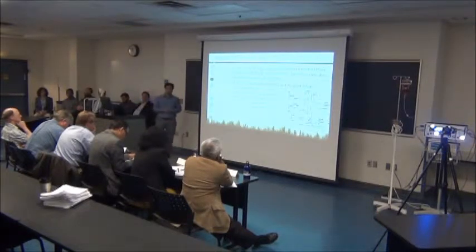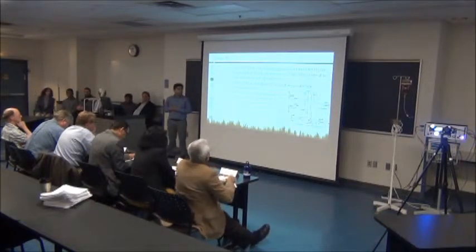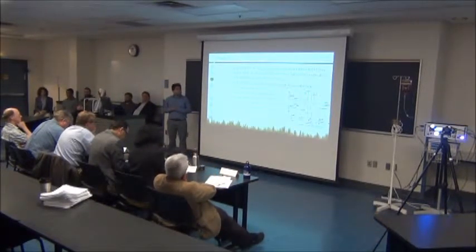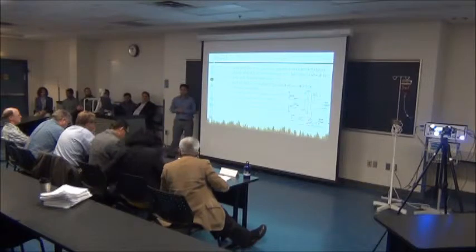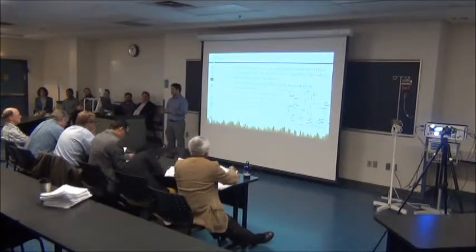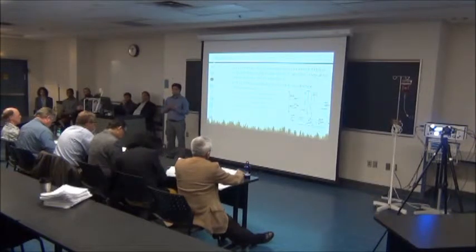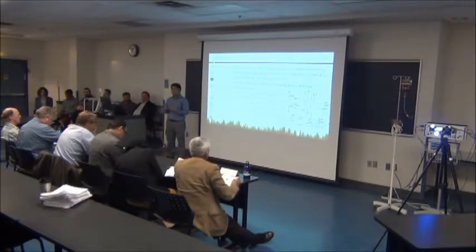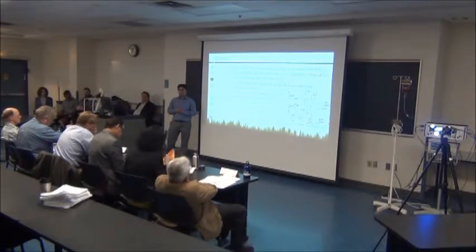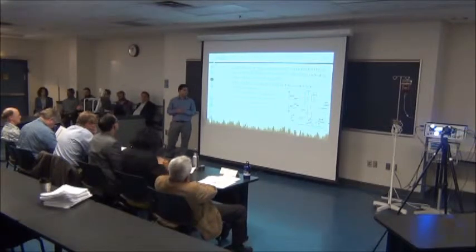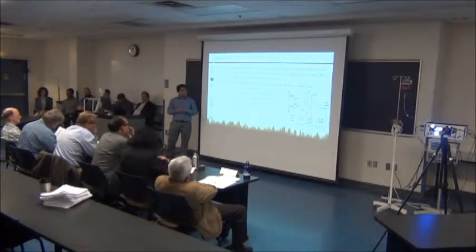Stage one consists of the AD620. The main purpose of using the AD620 is its characteristics, which are compatible with the pressure signal, because the pressure signal has a very slow frequency response. Its frequency is almost less than 2 Hz, and it's a small microvolt signal, so it needs amplification. The AD620 has good input and output characteristics, and it does not affect the tiny signal.